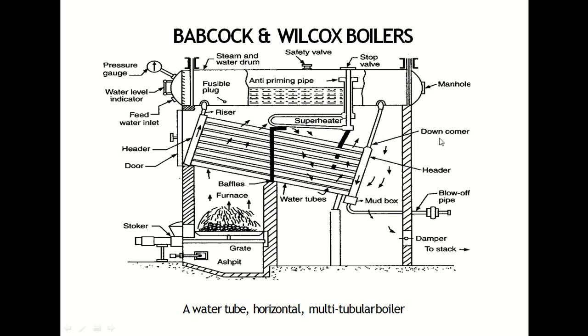Now here, this is the blow off cock. If there is some sedimentation or minerals in the boiler, that will be taken out from the mud box through the blow off cock. Or sometimes we remove all the water to empty the drum. Then you will use this blow off cock.